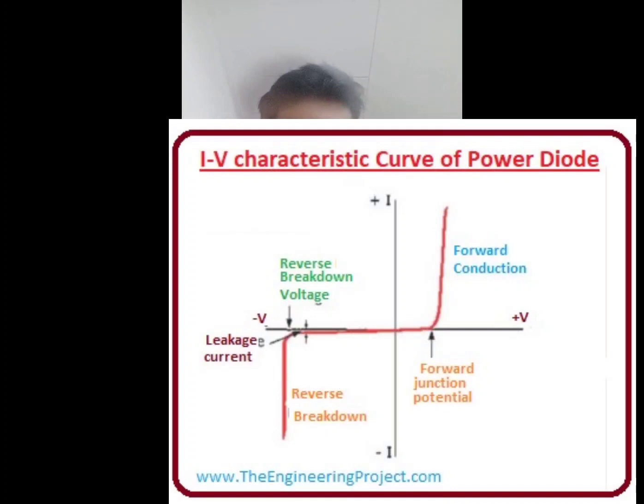We move to the working principle of power diodes. The working principle of the diode is similar to the normal PN junction diodes. When the voltage of the anode terminal is higher than the voltage of the cathode terminal, the diode conducts. The forward voltage drop in this diode is very small, approximately 0.5 volt to 1.2 volt. In this mode, the diode works in forward characteristic.